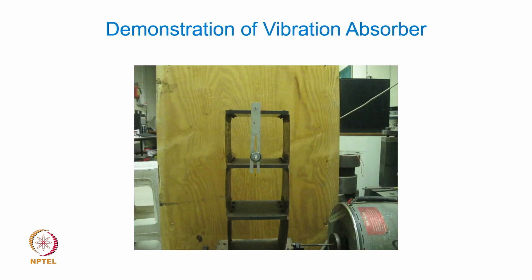imitating a multi-floor building. Of course, we cannot go to 101 floors. We have managed to have maybe 3 floors here, first, second and third, and it is mounted on a base which you can see here, and this base is excited by an electrodynamic shaker. So this is a shaker horizontally placed, and that shaker has a piston that oscillates at a given frequency and amplitude. So the base of this whole building is harmonically moved back and forth,